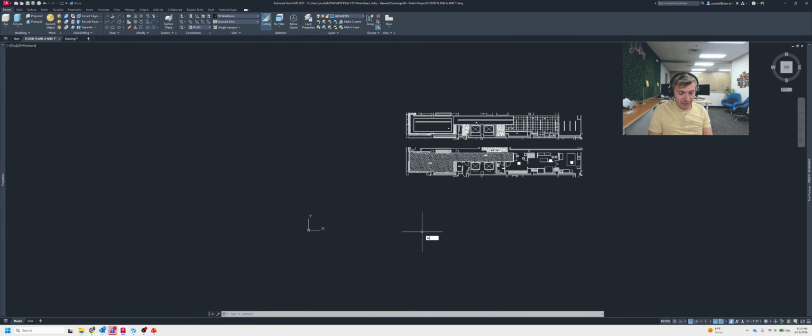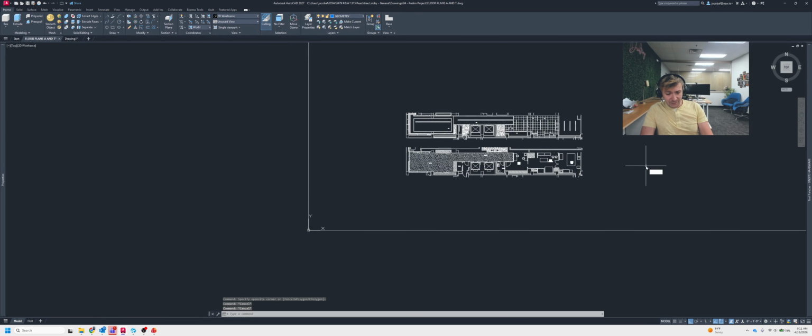I like to make my own grids for this because they don't fit within the standard drawing grids, since these are extremely large prints. So I'm going to type in Ray here to create a grid real quick. I'm going to start at 0,0 and drop two lines just like that. These two lines, we'll put on the viewport layer so they don't plot.